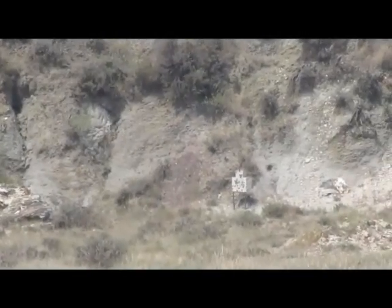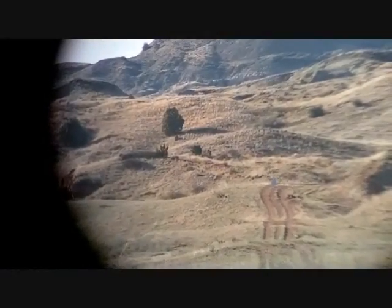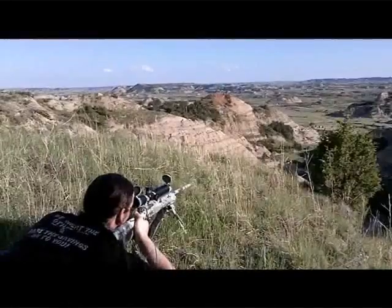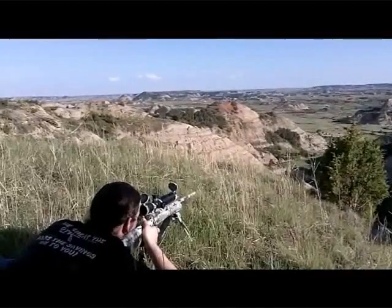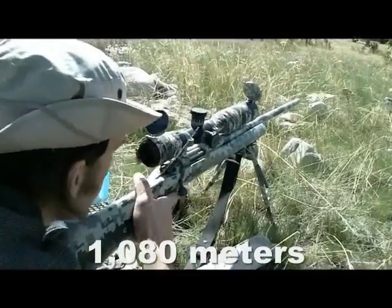So even with the really solid stocks like the chassis systems, the whole point of those is to get everything away from the barrel so that when it vibrates, your last point of tension is at the receiver, which is going to be solidly mated, and you're not going to have vibratory inconsistencies introduced along the length of the barrel, because that can be a nightmare to deal with. So the best way really to take care of this, in my opinion, is to free float the barrel from the stock. Just get rid of all those possibilities. Then you can be at peace when you pull the trigger. You don't have to worry about all that stuff.